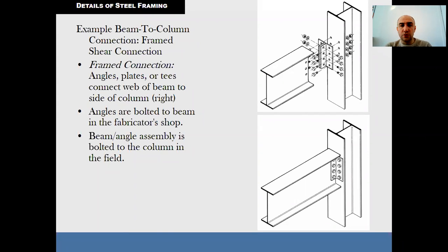In braced multi-story buildings, connections may account for less than 5% of the frame weight and 30% or more of the total cost. So an efficient connection will have low detailing, fabrication, erection, and labor cost.